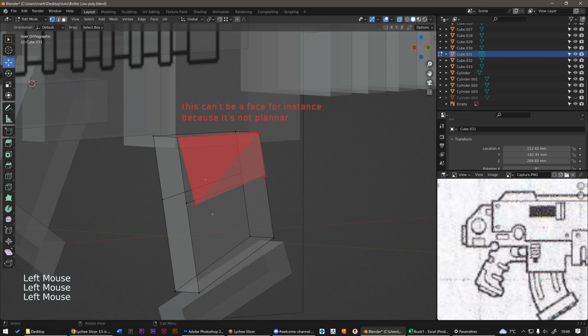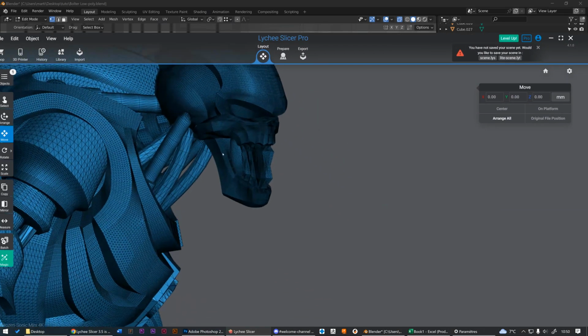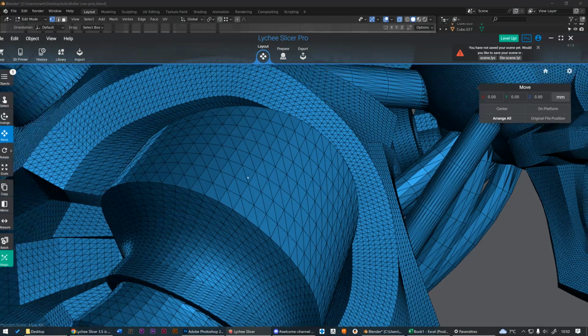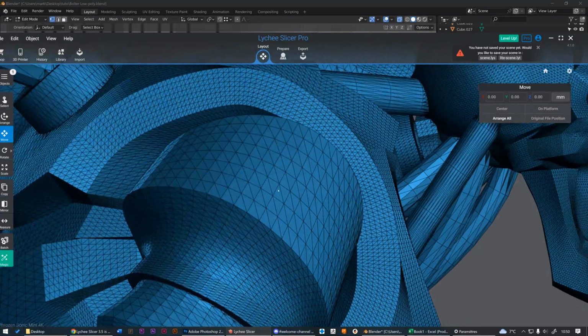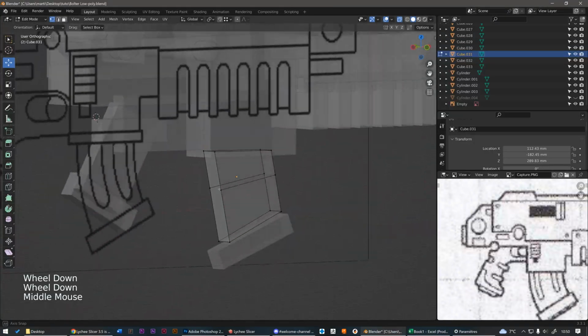A face must be flat, and having more than 3 edges does not guarantee a face is flat. That's why when you load an STL into a software that isn't a real editor like a 3D slicer, you see all the square faces have been split in half, because actually a square face doesn't exist. A face is necessarily a triangle.